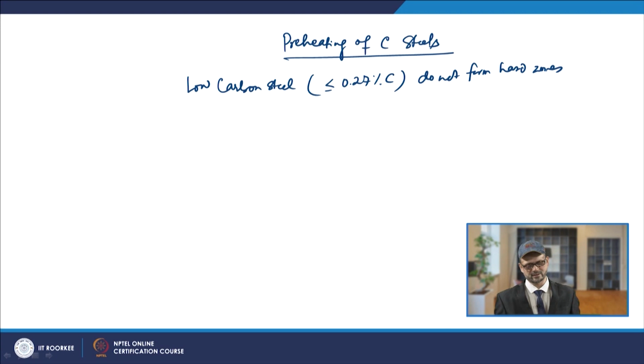They are usually not hardenable enough to require heating before welding, because when steels are more hardenable, you need to do preheating.